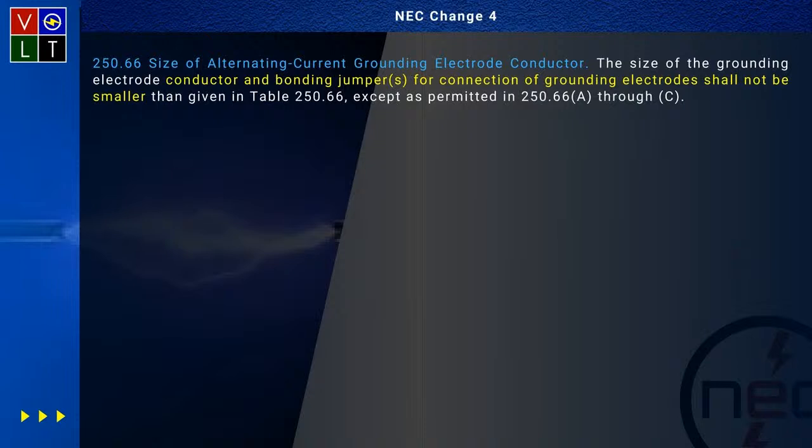And this is helping clarify that. Just putting in bonding jumpers helps clarify it. Yeah. Because they realize what you're going to and you're bonding the system in. But when you go look at the installation rules in 250.64, it's going to have to be the largest size that's connected over the terminal bar where they're making those connections anyway.